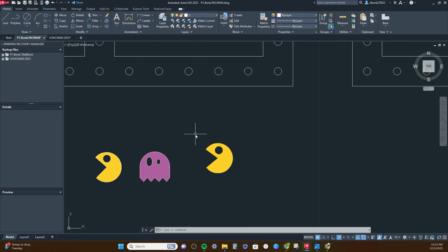After you finish each one of these characters here, what you want to do is click on one side, drag the mouse down, click again on the other side. You can see it's selecting all these different parts of this construction here we've got. And you're going to click the group button, and it's going to lock all of those drawing parts together. So when we go to move PACMAN or whatever else, gotta select it first.